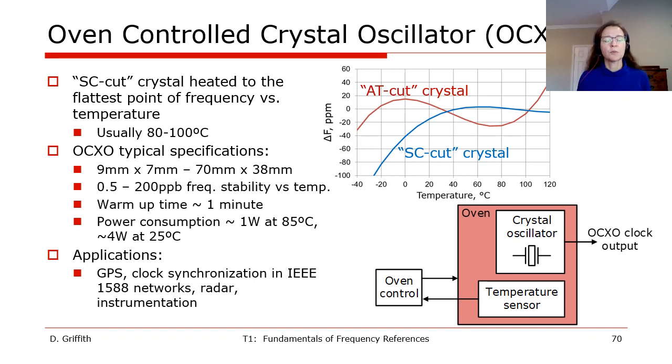In the crystal oscillators we discussed earlier, the AT-cut crystal was most commonly used for the megahertz frequencies, which gives a frequency versus temperature curve that's a cubic, as shown by the red curve on the plot. However, it's also possible to cut the quartz crystals in a shape called the SC cut, which gives the curve shown in blue. So obviously the blue curve has worse performance at colder temperatures. However, at the higher temperatures, it's much more stable.